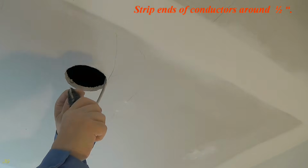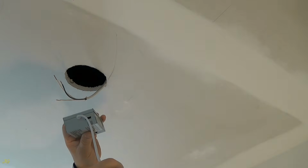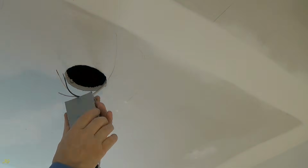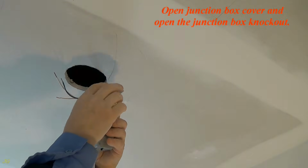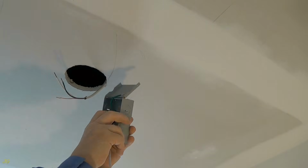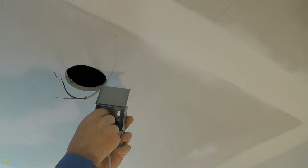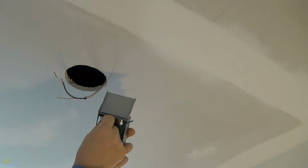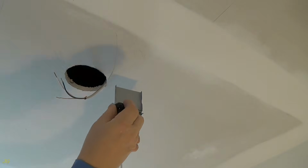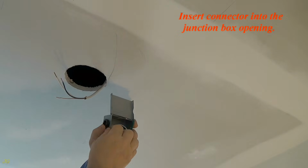Strip the ends of the conductors around 1/2 inch. Open the junction box cover and open the junction box knockout. Insert the connector into the junction box opening.